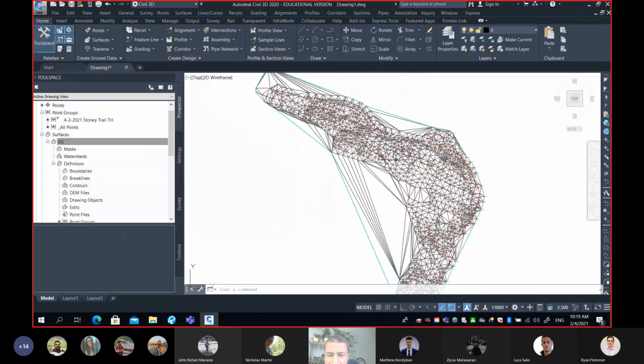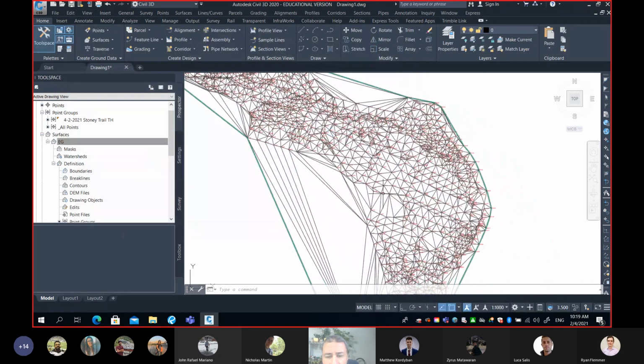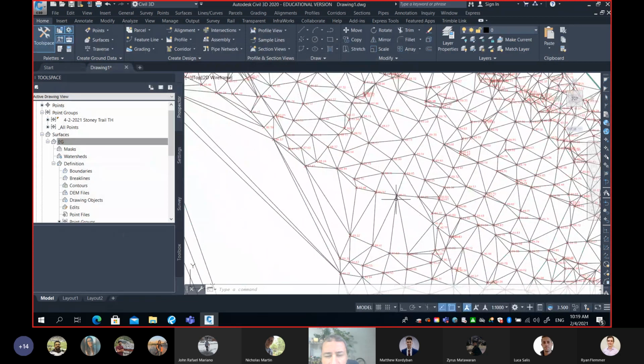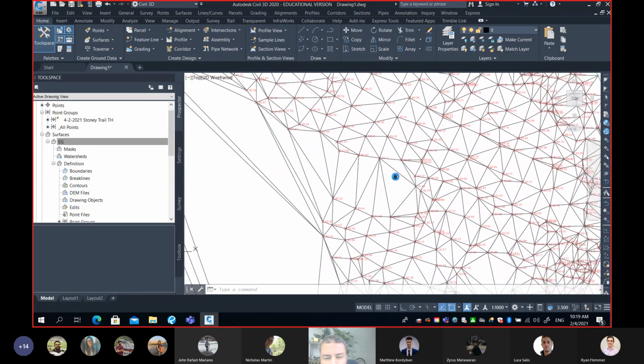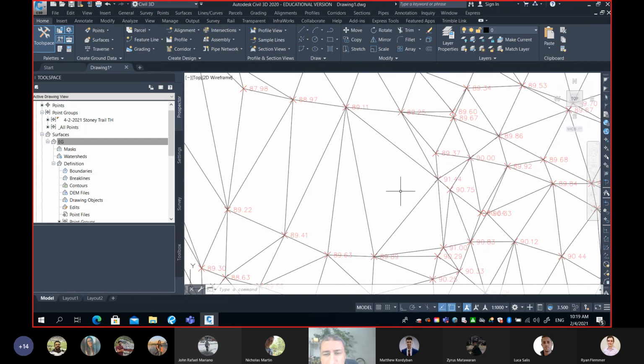Now you can see here is my surface, and there is something we already discussed last class, which is interpolation and extrapolation. My conclusion is that in surveying, interpolation is acceptable. If I ask what the elevation of this point is, it tells me 90.137.